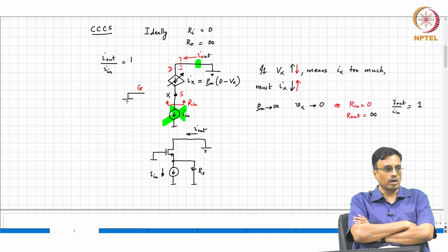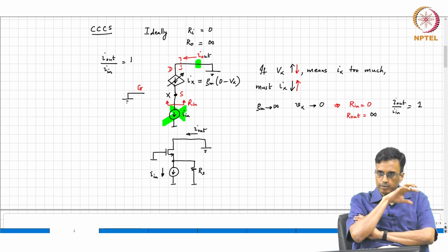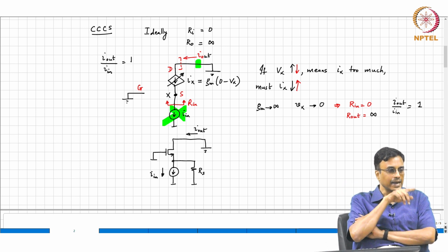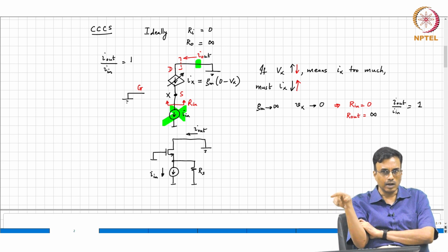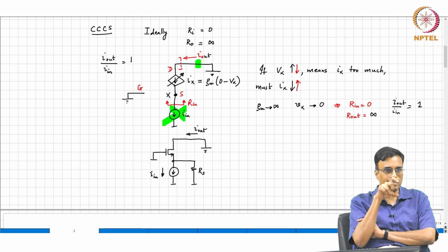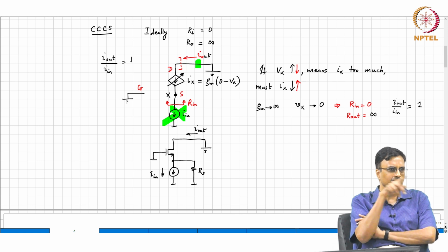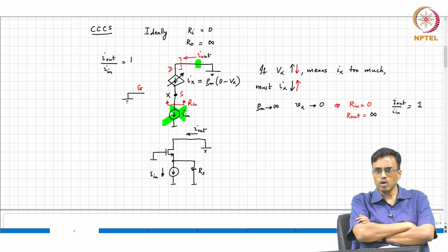Okay. So, if you connected a bad current source to a load, ideally you would expect that all the current provided by the current source must go through the load. But unfortunately, because the current source is bad and it's got some internal impedance of its own, all the current will not flow, only a fraction of it will flow through the load, correct?